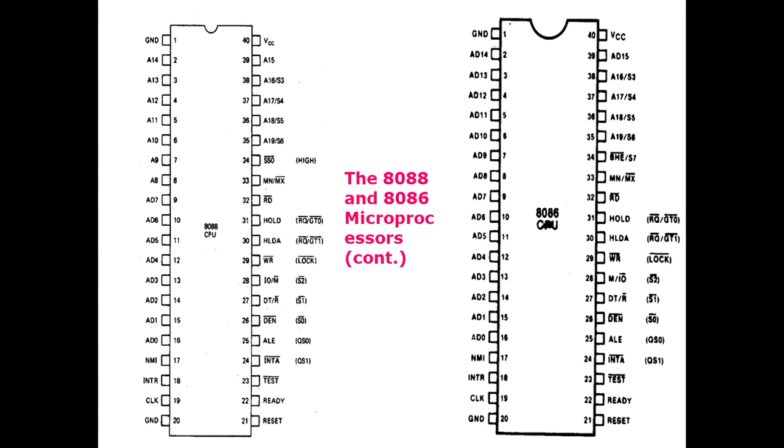The operations and signals of addresses generated by those instructions are then externally connected with the external buses, control bus, data bus, and address bus, through a number of pins. These pins are given in dual inline packaging, where the microprocessor has pins on both sides.